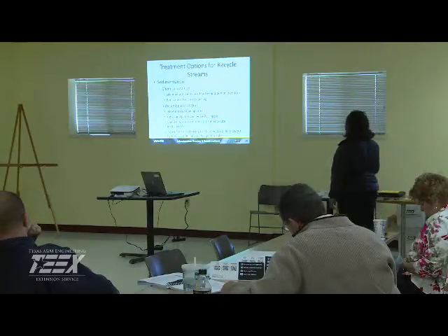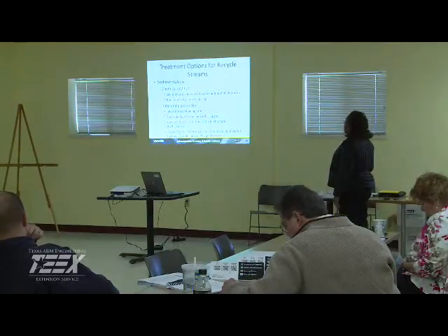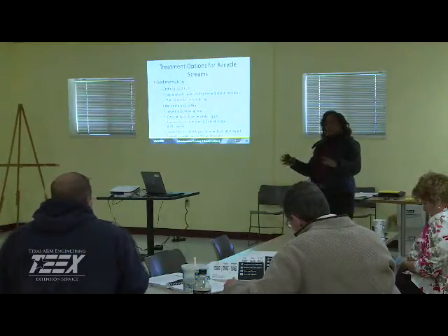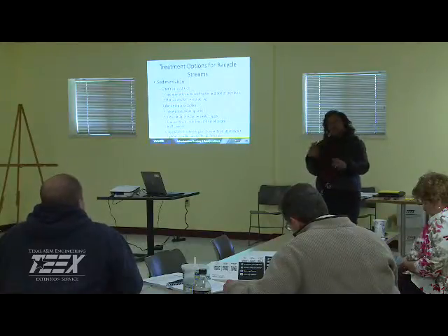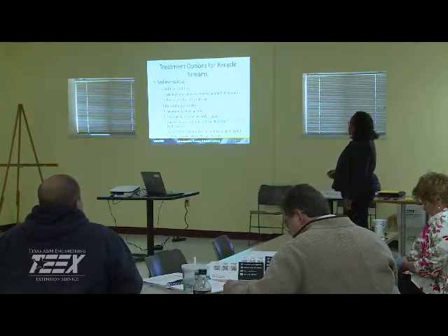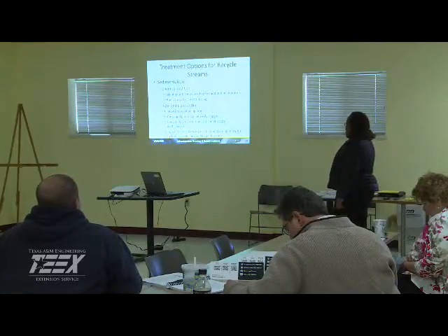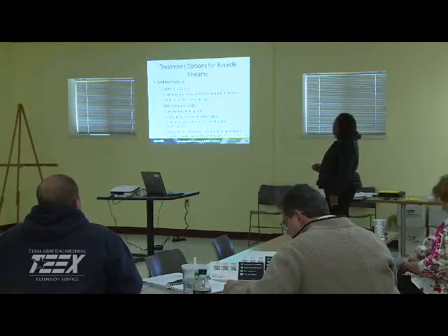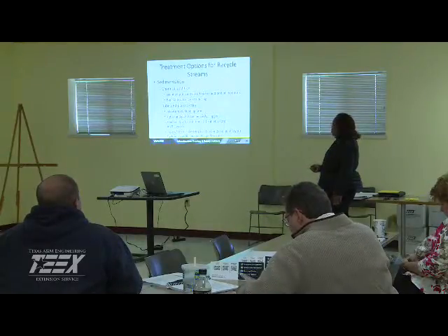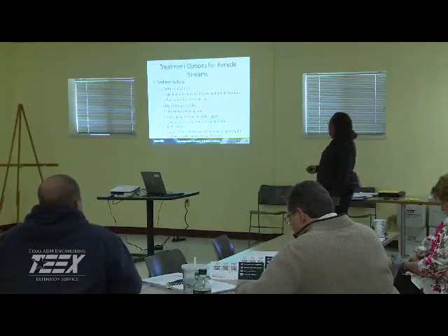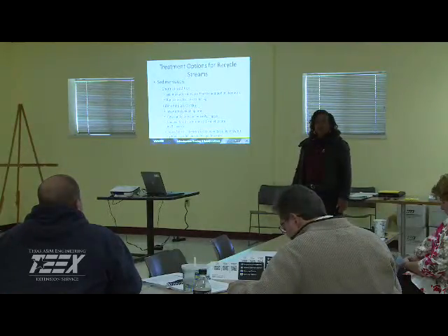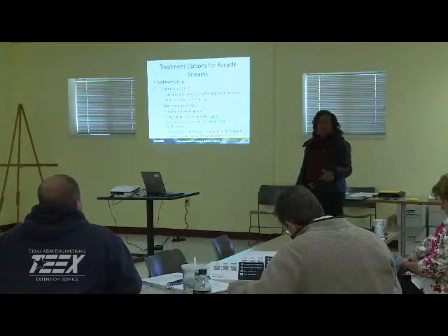Tube and plate settlers. Some people believe these are a lot better than your traditional sedimentation because you don't have to have that surface bottom. You have all these tubes where you have a much wider surface area, so it allows for greater loading rates. One of the disadvantages is that your tubes and plates can easily clog, or uneven flows can create inefficiencies. The type of chemical mixing used depends on the plant layout, your hydraulic grade line, and design flow rate. So you probably need a little more experience in order to operate these than others.